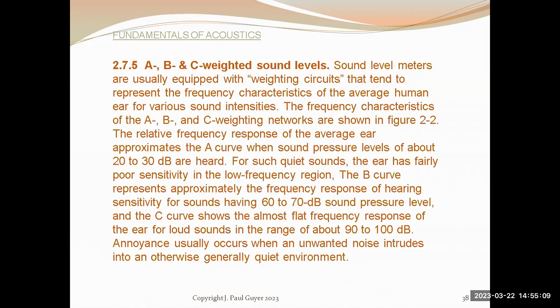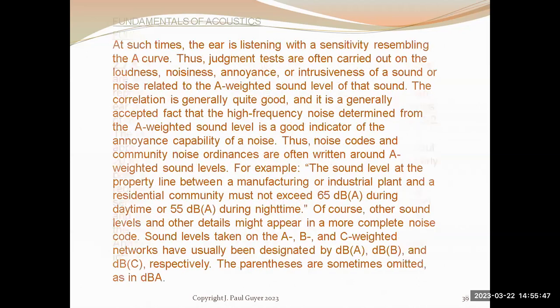If you set it on the high level, the sound level meter will sample the sound about every 1/8 of a second. And there may be some specialized situations where you would want to use that fast sampling rate, but with typical building design, you're going to set that knob on the slow setting. Okay, and now the other knob, the ABC knob, let's move forward.